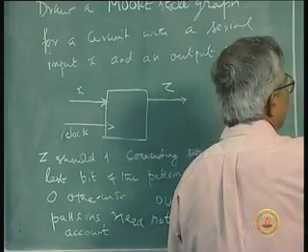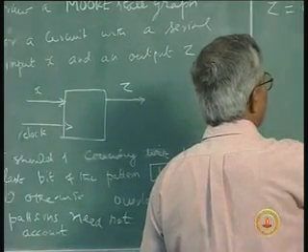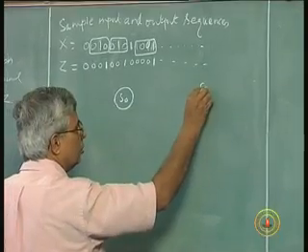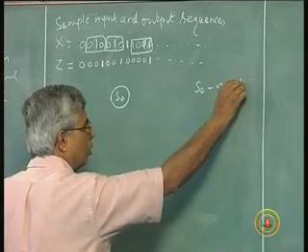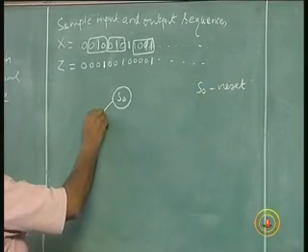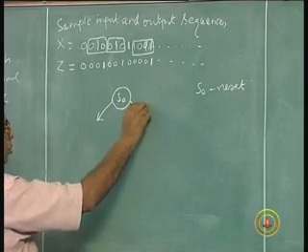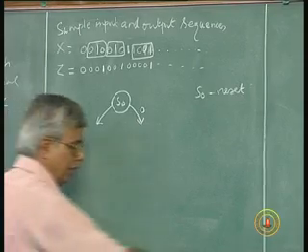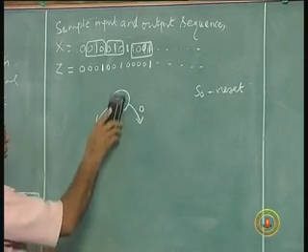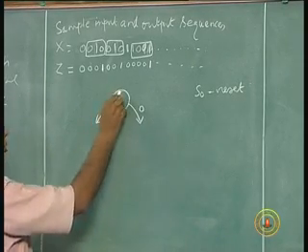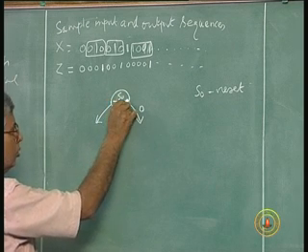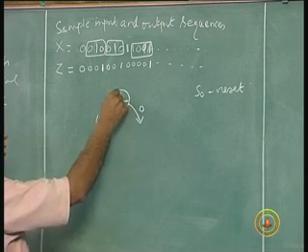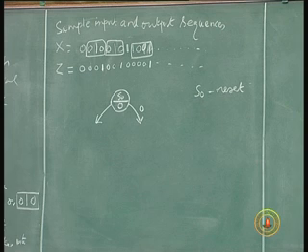So, let us start with S0, the reset state. Now, I do not have to draw the output on an arrow. I have to draw the output within this state. So, usually you put S0, that means in this S0 state the output is 0. Along the arrow we mark the input, inside the state you mark the output.